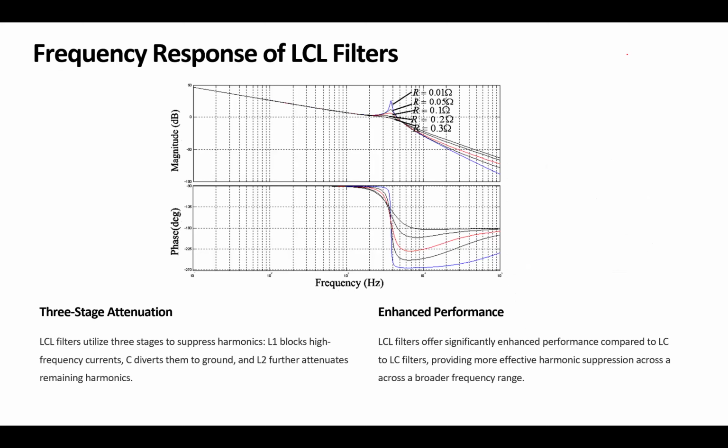Now, there is one thing that you have to be careful about when you have LCL, and it's the resonant frequency, the natural frequency of LCL.